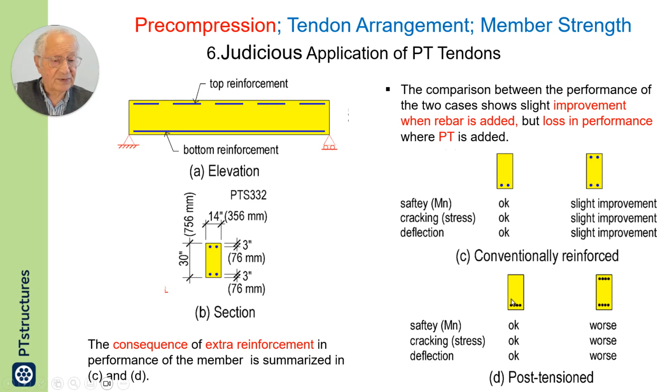Why does it reduce the capacity of the member? Because in the compression zone, you have introduced some tensile force, which takes away from the concrete compression that can be developed there.